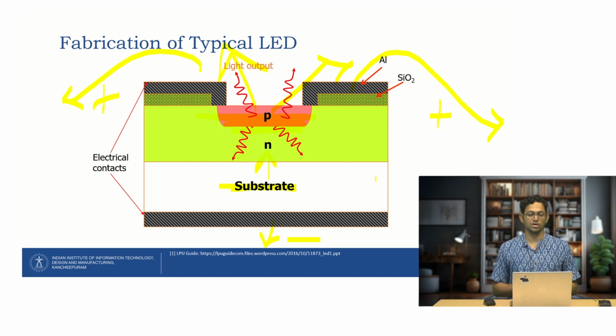How does the light emitting diode work? Okay, so in the next session we will talk about how the laser works and how a laser is quite different compared to the light emitting diode. As we discussed, a light emitting diode is a spontaneous emission, but when we talk about laser, we will see that laser is a stimulated emission, which means that we can control when the photons are being generated. We can control it in such a fashion that all the photons are generated at a single time, instantaneously together, and then their multiplication can happen again at a single time, all at the same time. And that is why the intensity of the laser becomes very high.